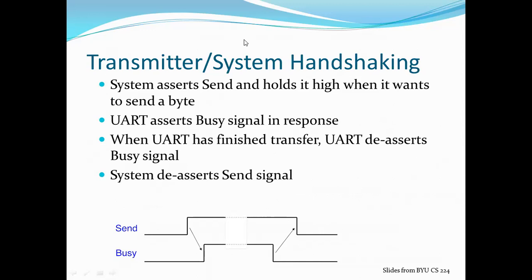UART asserts a busy signal in response. Whenever the UART finishes the transport, it deasserts the busy signal. Then the system deasserts the send signal.